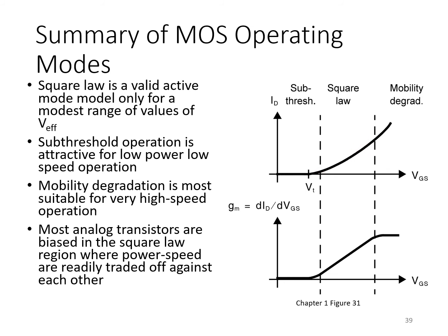I think that helps focus your design effort and gives you a guide for selecting operating points for all the transistors in your circuit. You keep this picture in mind and think, for this particular transistor, do I want a lot of transconductance? Do I care how big it is? Am I really limited by power, so I don't want to bias with a lot of current?